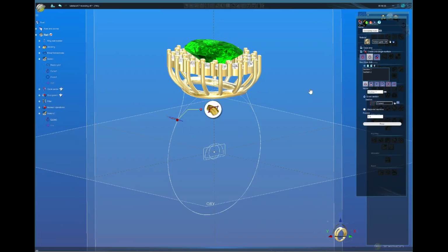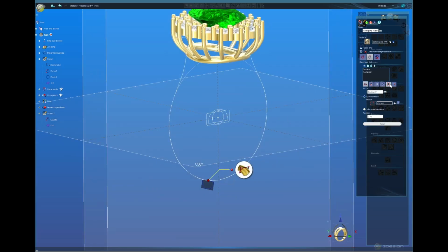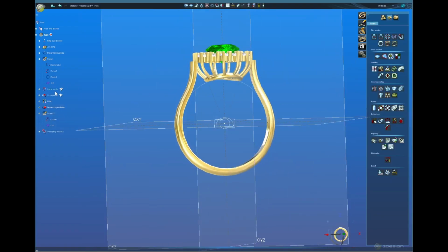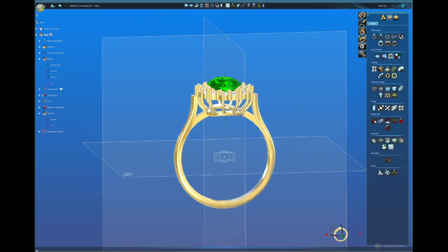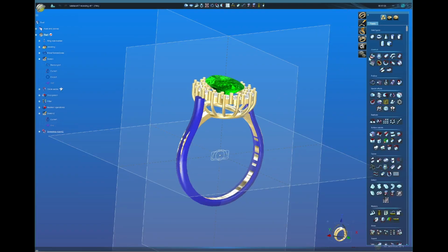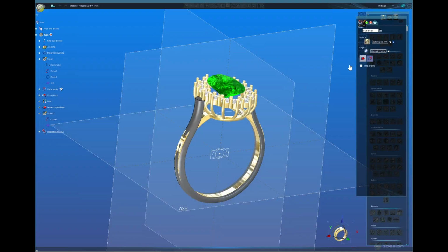And I'm going to get one more, bring all the way over here to the bottom. And for the bottom, we're going to do 3 millimeters by 1.5. And we click OK. And that's our shank. Let's bring the inside shank just to look better. So we're doing good. Let's get the outside shank, and we're going to do a bulge